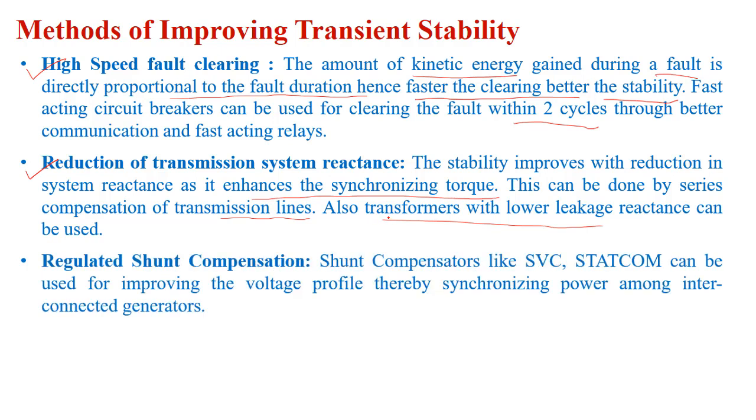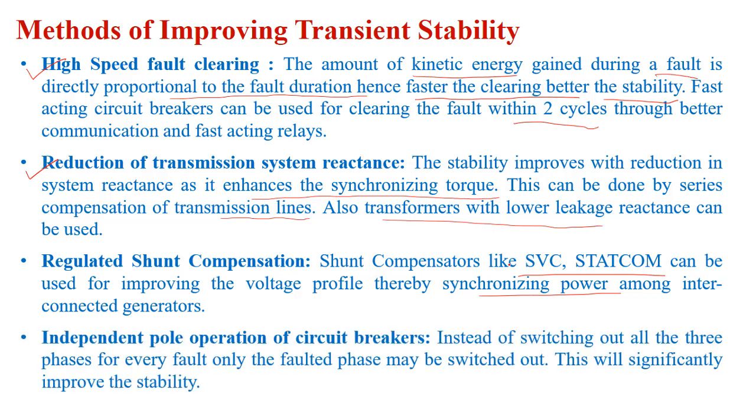Shunt compensators like SVC and STATCOM can be used for improving the voltage profile, thereby synchronizing the power among interconnected generators. So SVC and STATCOM, they are the shunt compensators. They are used to maintain the voltage. So this helps us in fact in synchronizing the system.